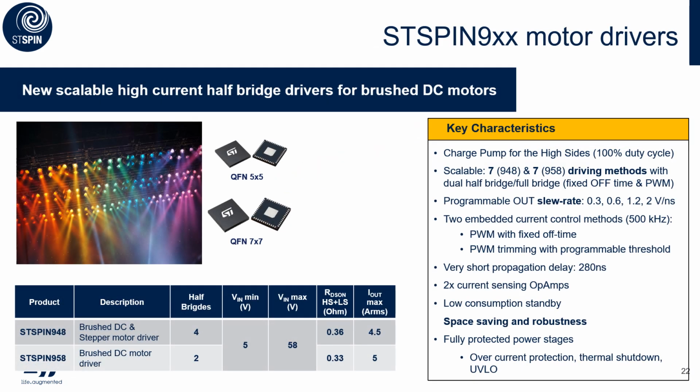The STSPIN9X8 family is a multi-half-bridge motor driver family for brushed motors and bipolar stepper motors with a single and a dual full-bridge version. The power stage of both products is designed with high dynamics, allowing high-frequency PWM control with precise duty cycle. This is guaranteed due to a charge pump which allows the driver to go to 100% duty cycle. The device